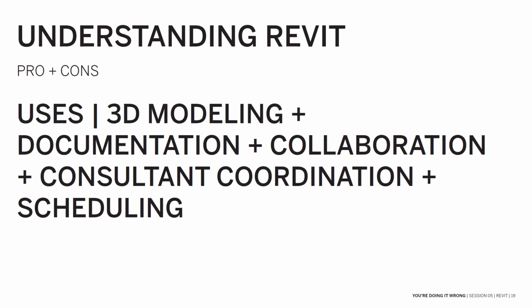Some other things that Revit is used for, obviously, is 3D modeling, but also documentation, so construction documents, design development documents, schematic design, all of that documentation can be done inside Revit. All the sheets that you need for your construction docs can be done inside Revit. It's amazing for collaboration and consultant coordination, so multiple people can work on the same Revit model, and that works on an ownership basis. And there's also scheduling, so creating door schedules, window schedules, or other building element schedules can be done inside Revit.